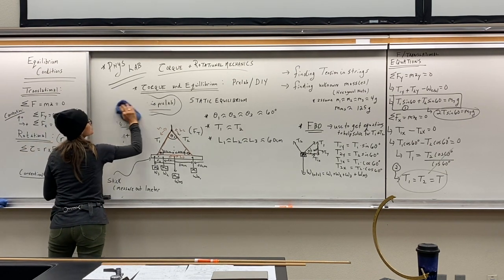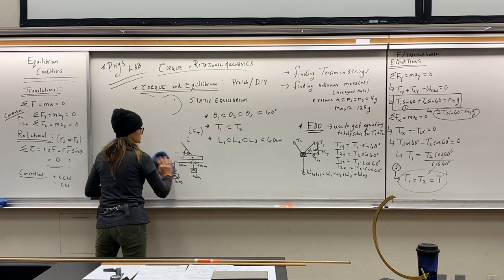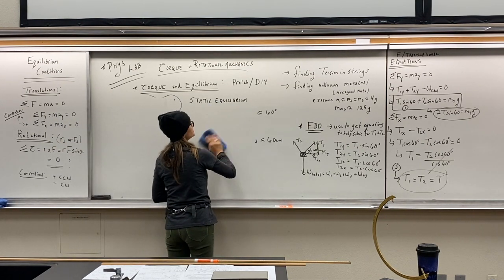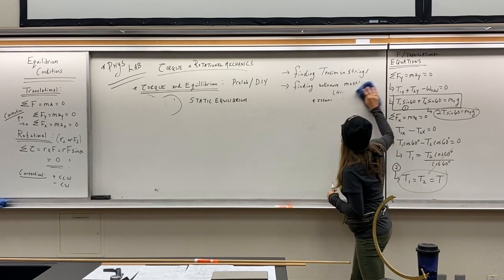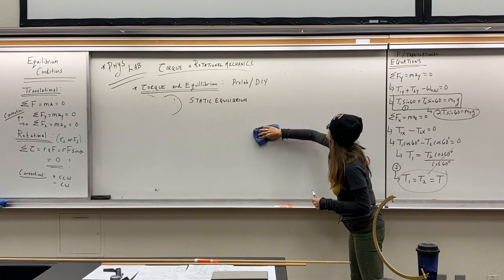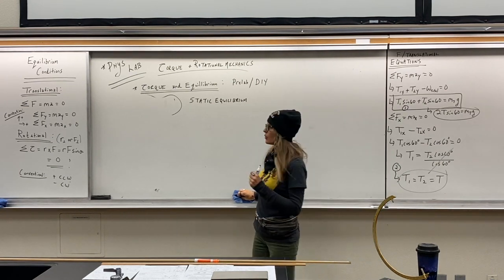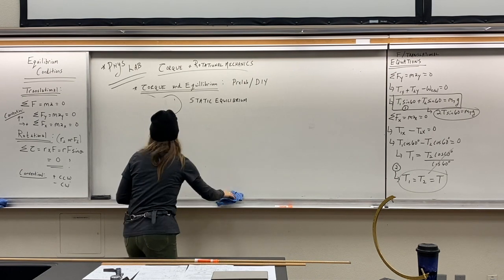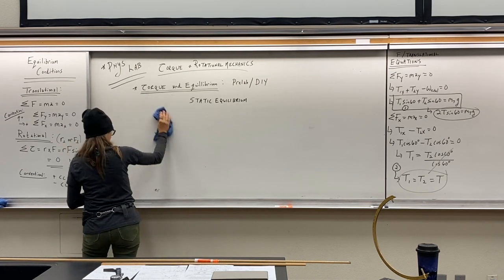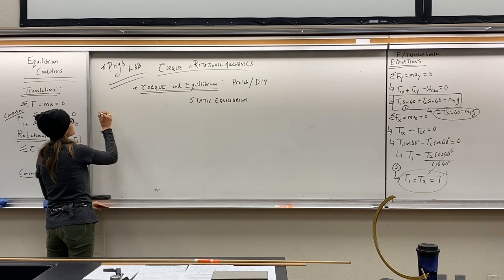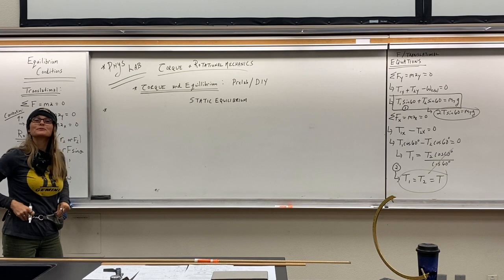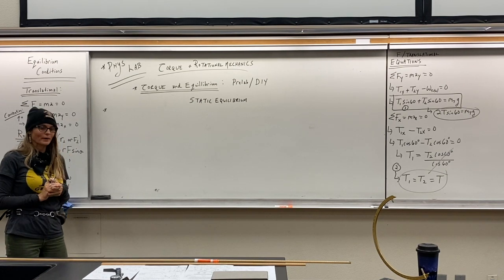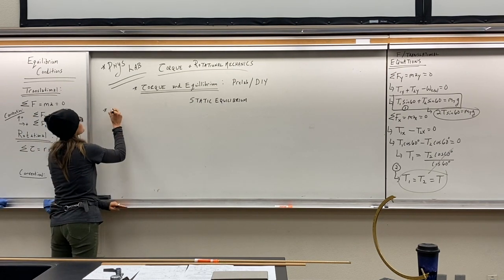So I'm going to do a torque diagram. Notice I do a general diagram, a free body diagram, and the torque diagram is a little different in that you show the points of contact. Okay, so here's my torque diagram, and I cannot emphasize enough the importance of doing a torque diagram when you're doing rotational mechanics, when you have to include torques in your equations. So here's my torque diagram.